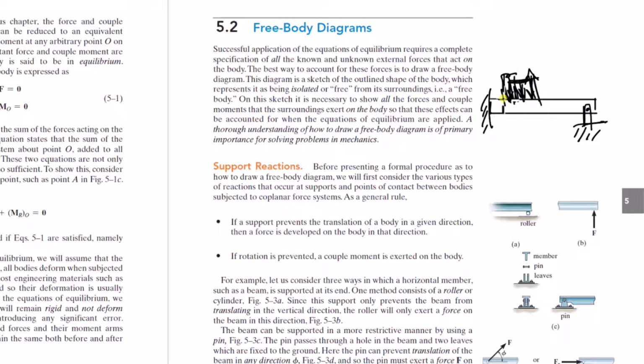If any component of a net force applied by something is this equal and opposite pair of forces separated by a distance, you just turn that into a couple moment. So all you're left with is the translational portion of the force and the spinning portion of the force.